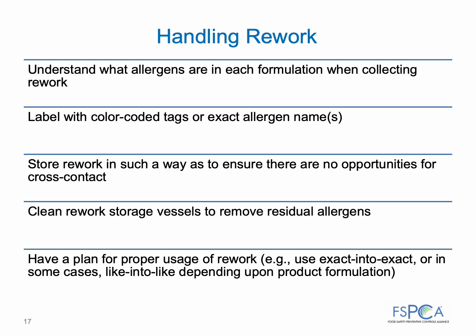To reduce opportunities for cross-contact, use sturdy containers with secure covers and interior disposable plastic liners where appropriate. Use dedicated containers, lids, and pallets when feasible, or thoroughly wash and sanitize containers before reuse. Using containers that are easily moved without use of equipment to hold allergen-containing materials, e.g. totes on wheels, makes it easier to segregate the material and reduces the potential for damage by forklifts.